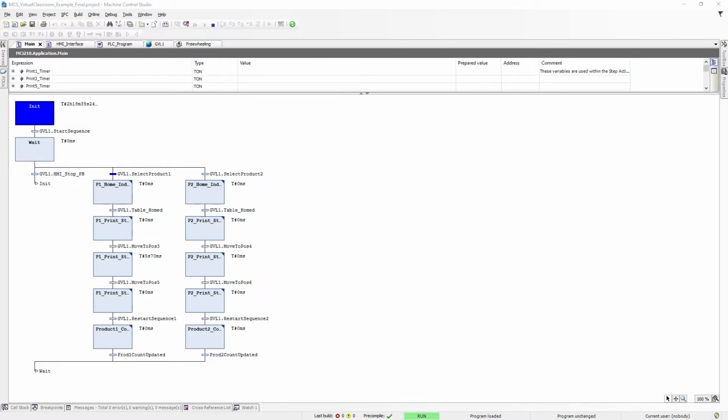And then my next thing was, obviously we have a reset and then a status of whatever. There'll be various signals that can trigger that status and display whatever the problem is. Then the other thing was, in terms of the AMC with an HMI, I still want to have a user interface, so that would be a push button that goes straight to the AMC for the go command, for instance, as opposed to the HMI. Is that sort of a good practice?